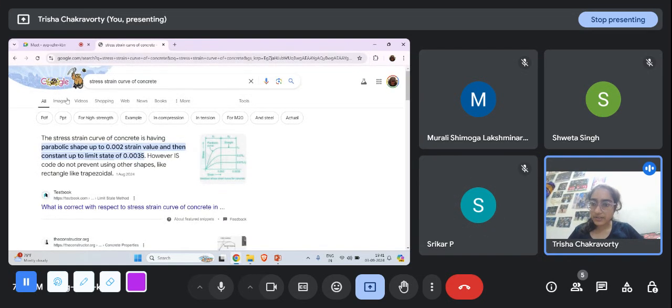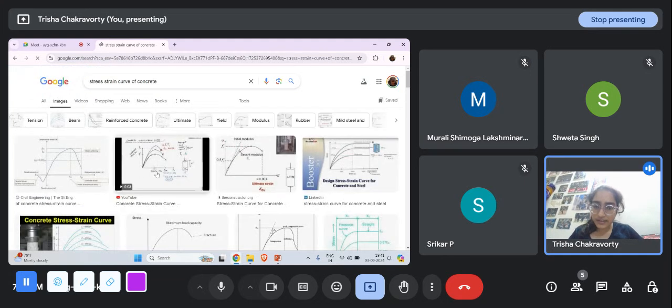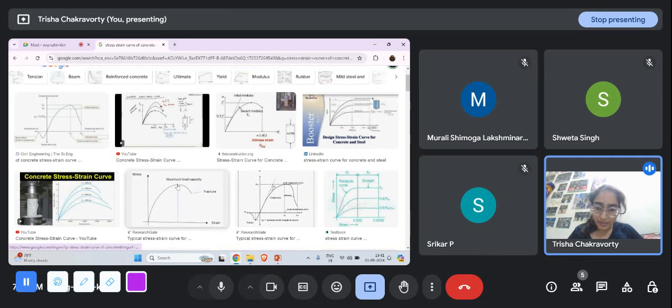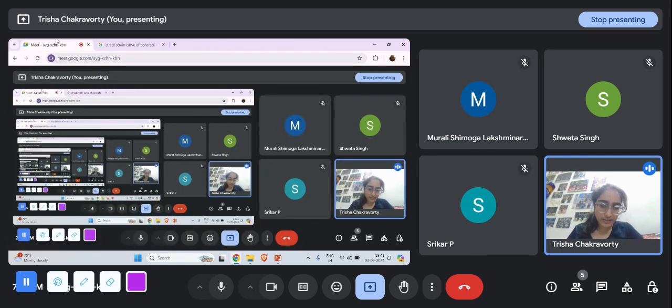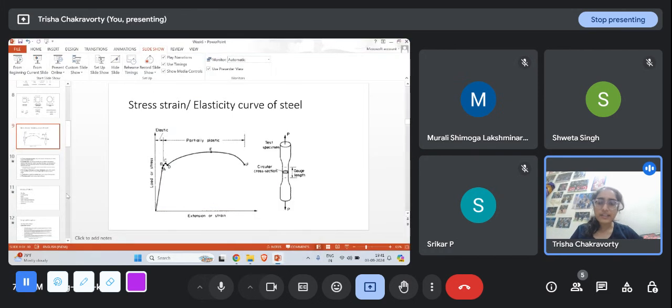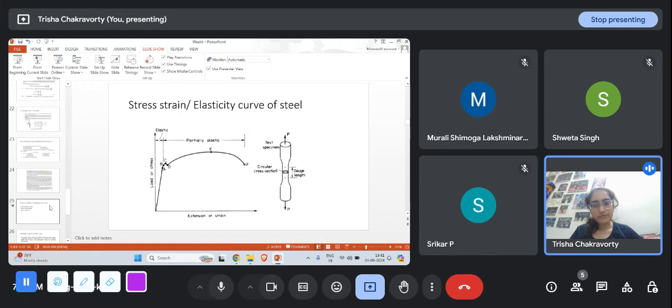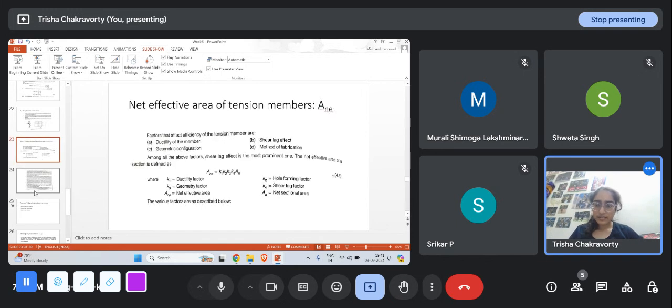We have looked at this already. Look, the stress strain curve of concrete goes here and it abruptly ends after yielding. Immediately after yielding it fails, while the steel goes a lot further, so concrete is comparatively a lot more brittle than steel. I don't think they can be directly compared by this K1 factor. This K1 factor and all these stipulations that we are studying are applicable only for steel structures. But K1 will be much lesser for concrete and wood. In terms of ductility and brittleness, concrete is way more brittle than steel.